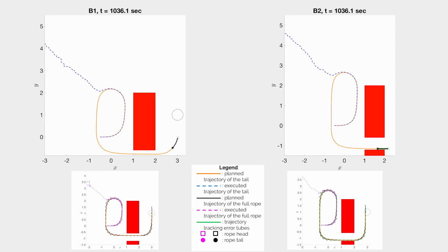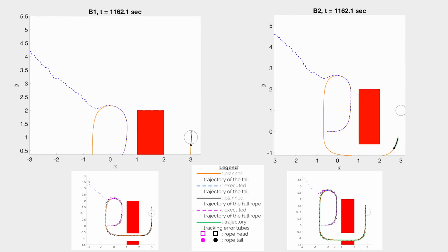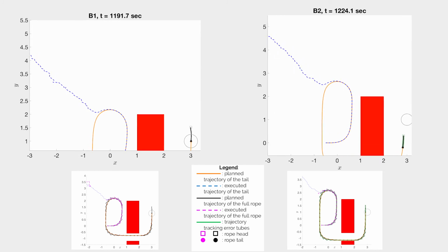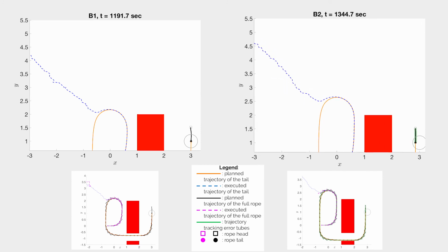B2, on the other hand, uses the maximum training error as the uniform disturbance bound. This can be restrictive, as seen in the previous examples, but is also not safe, since the model error in D can actually exceed that which is seen on the training set. This also leads to an underestimate of the model error, leading to the same unstable behavior seen for B1.